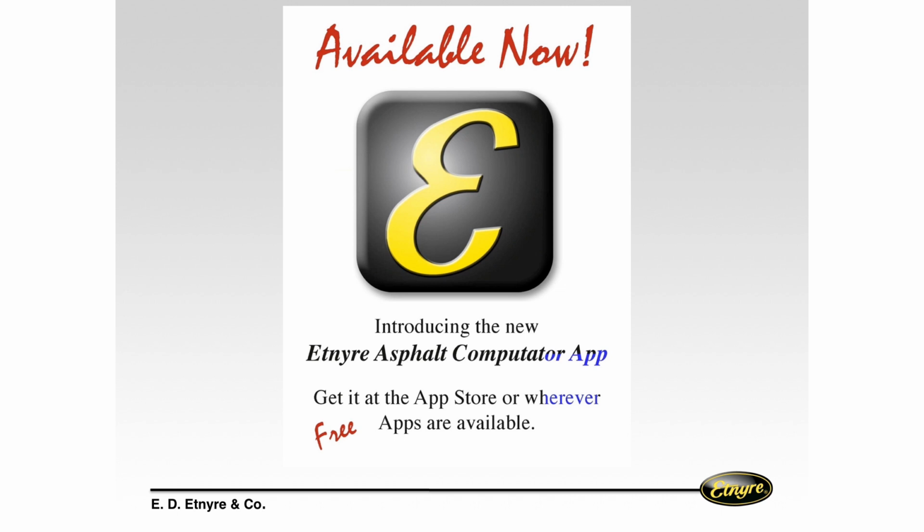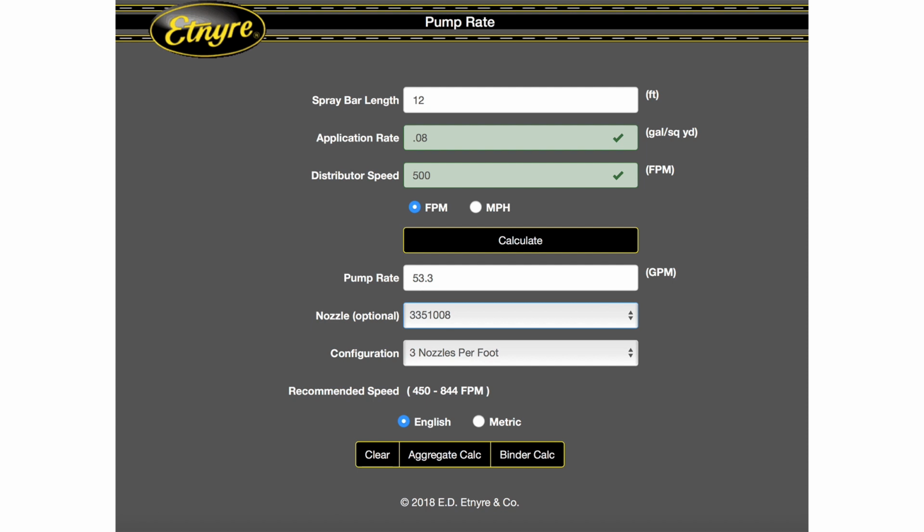Okay, so we have an app that is available now, free for download, that will help you on any job. It will let you pick out your bar length. You put in the application rate that you want, in this example 0.08, which is very common of what you're going to be shooting in Virginia. You pick out a distributor speed in either feet per minute or miles per hour.